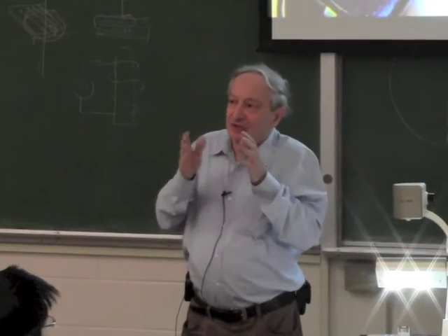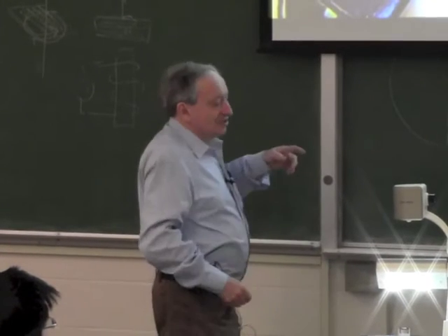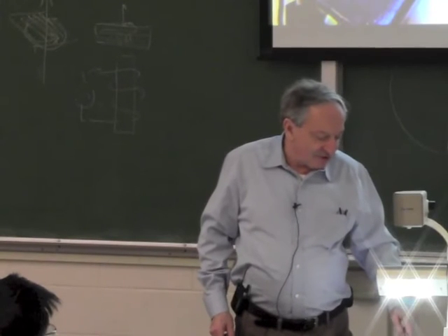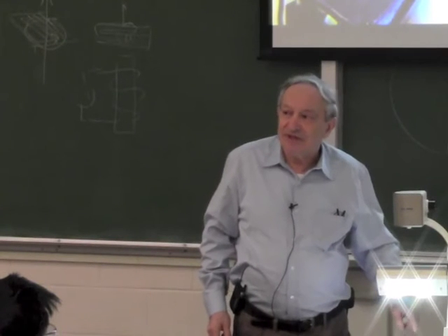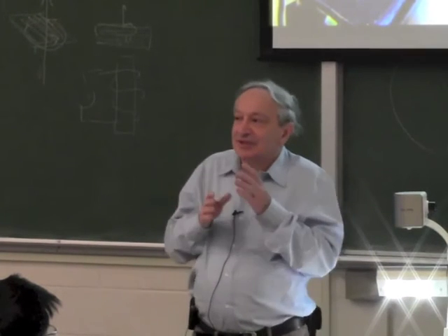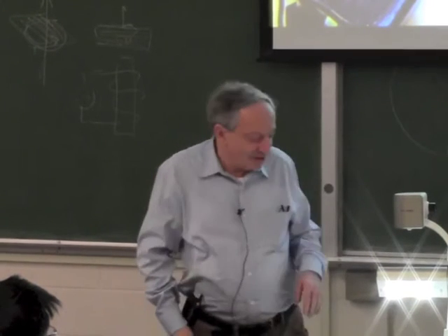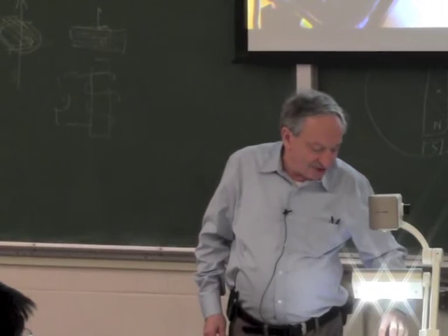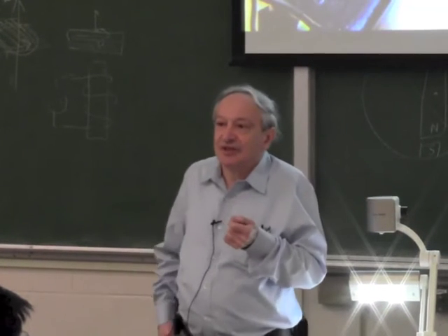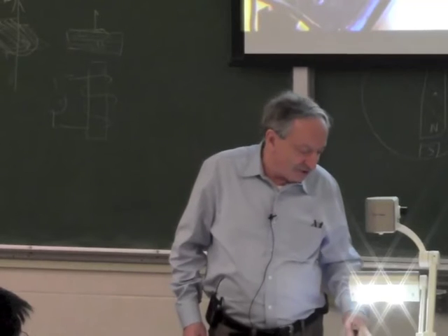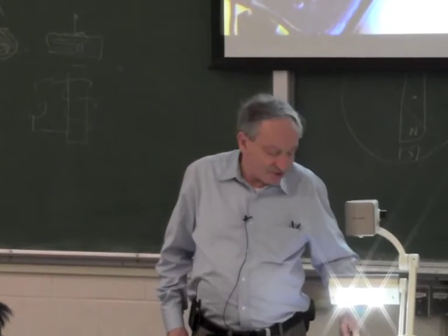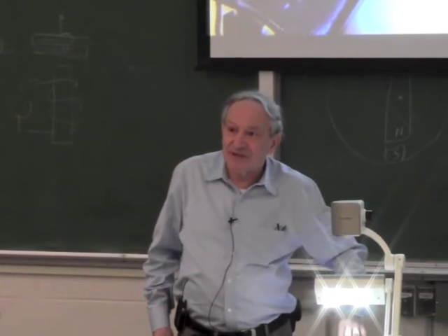I mean, roughly, it's not exactly 90 degrees, but roughly, since one of them generates a current based on the derivative of the main field, and the current creates its own field, there will be two fields, not exactly 90 degrees apart, but they'll separate because one of them impedes the change of current. The ring impedes or fights the change in current. So in one end, the field or the current can change easily. In the other one, the field cannot change easily because it induces a voltage in the ring, which impedes it.